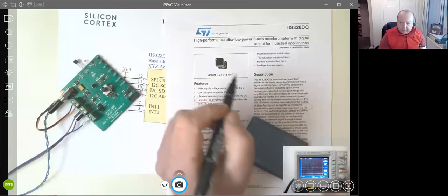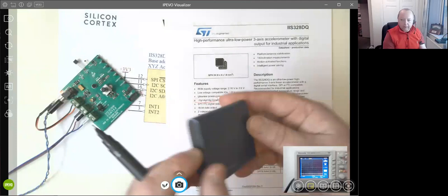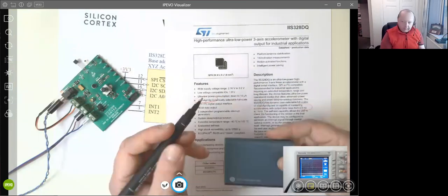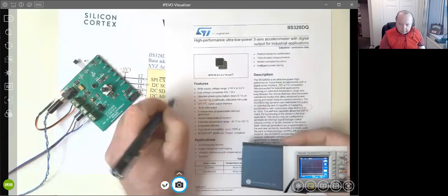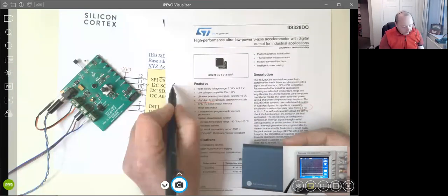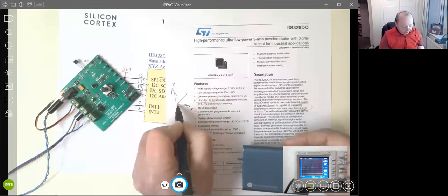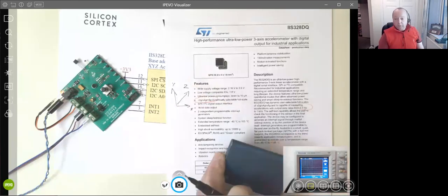But accelerometer chips can do the whole left-right tilts, and some of them go in 3 domains. So you can have the Y domain, the X domain, and of course some of them will come out of the page in Z. So again, it depends on what you want to do.